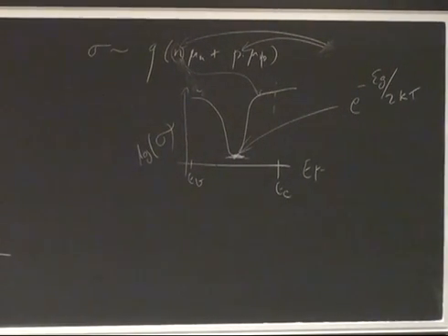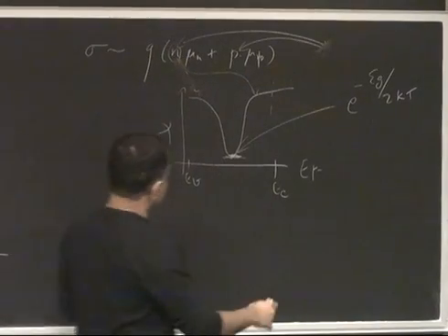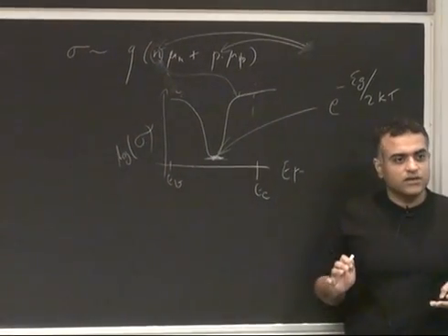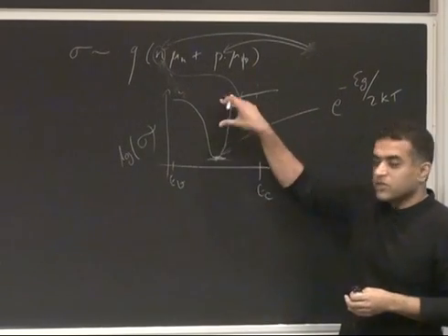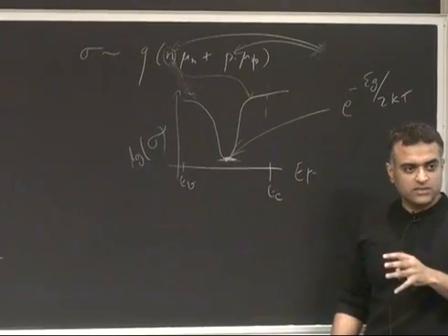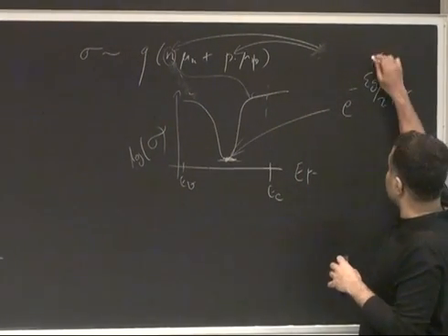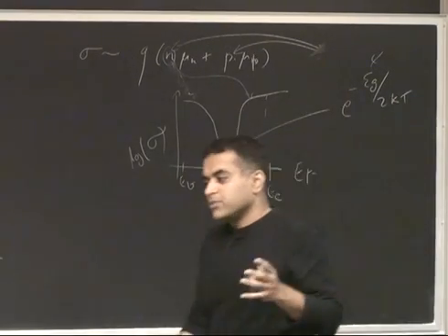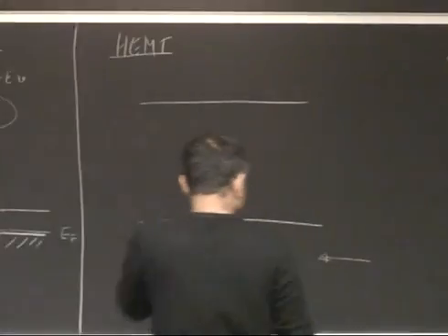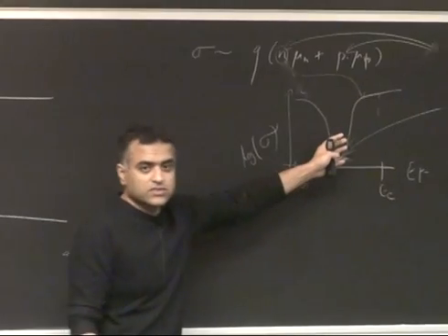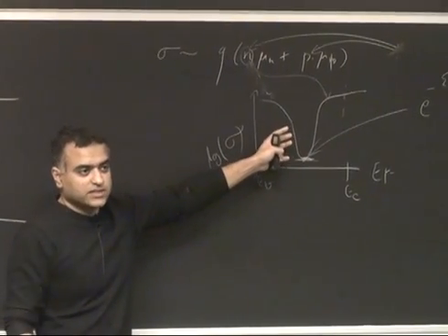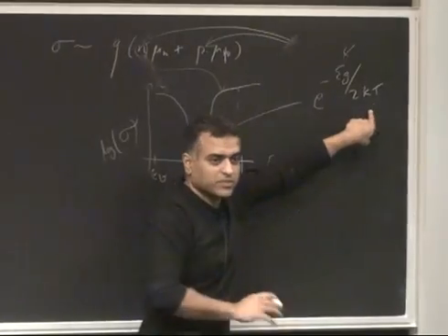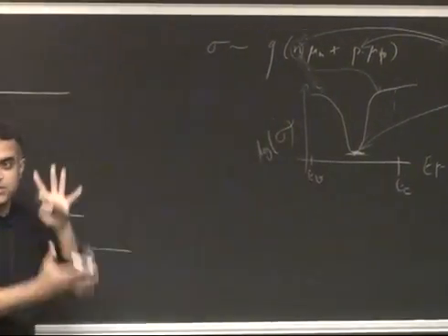Which means that just by pure doping, if you have a very narrow band gap semiconductor, say indium arsenide, you really cannot modulate it much. You can do the numbers, put in the band gap to kT. If you have a 0.3, 0.4 electron volt band gap, your modulation is hardly 3 or 4 orders of magnitude. You can actually calculate it at room temperature. If you take the temperature lower, no problem, you can modulate it more, but at room temperature, the modulation is limited.